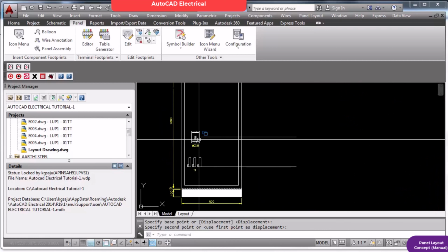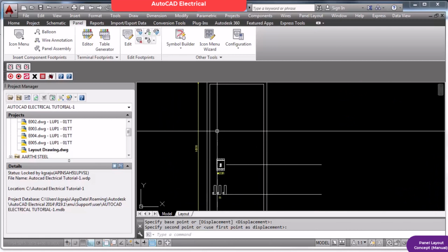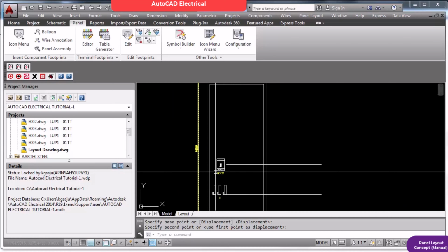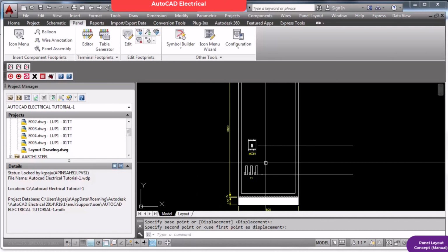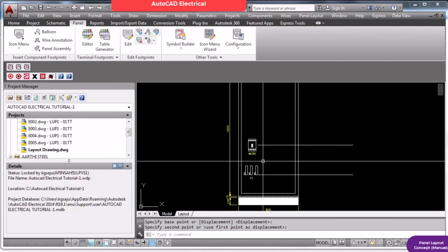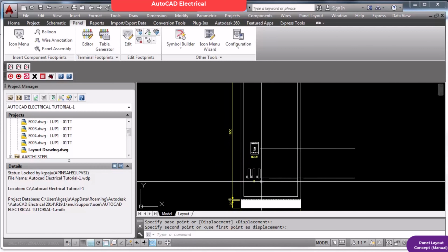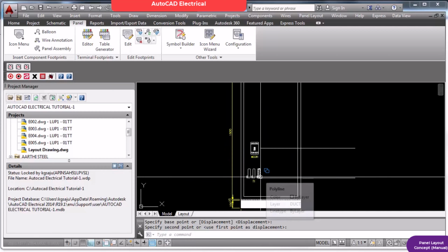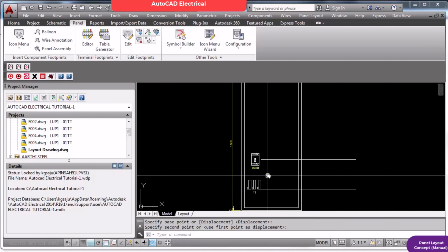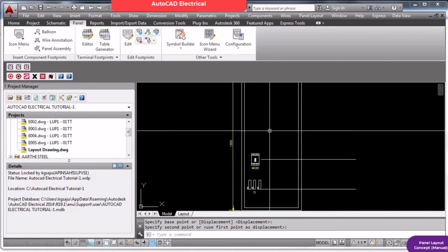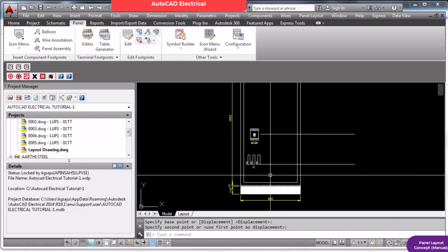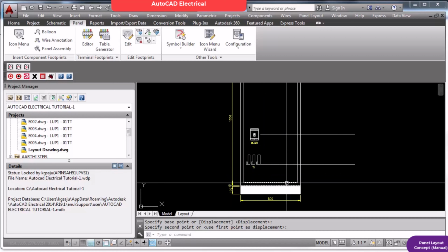Now it will go to the choke. If it is a small choke, of course you can mount it somewhere on the mounting plate. All these things are mounted on a mounting plate. Even you can use channels to mount, but in this case I am considering a mounting plate. The next thing I want to mount is a choke. If it is a small line choke, we'll call it line reactor, you can mount it anywhere in the panel. If it is a little bit big,